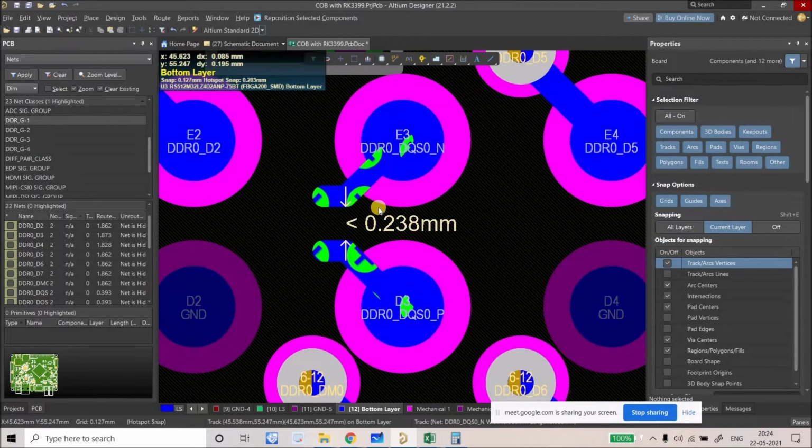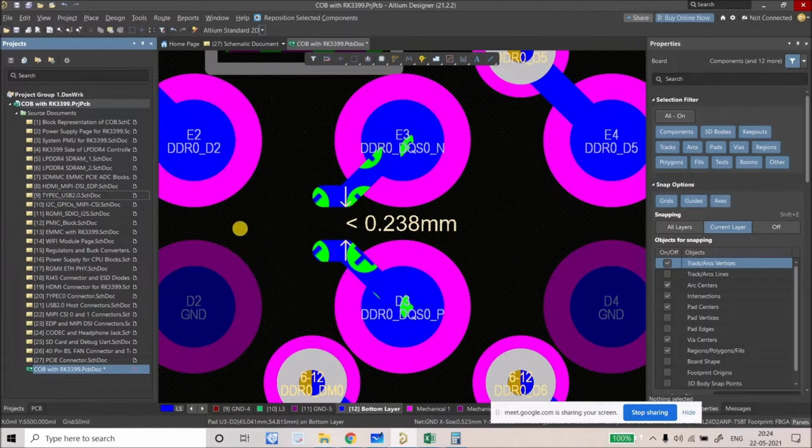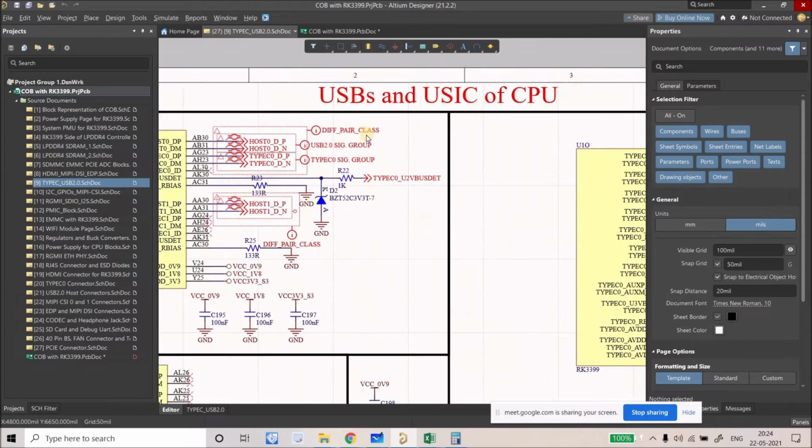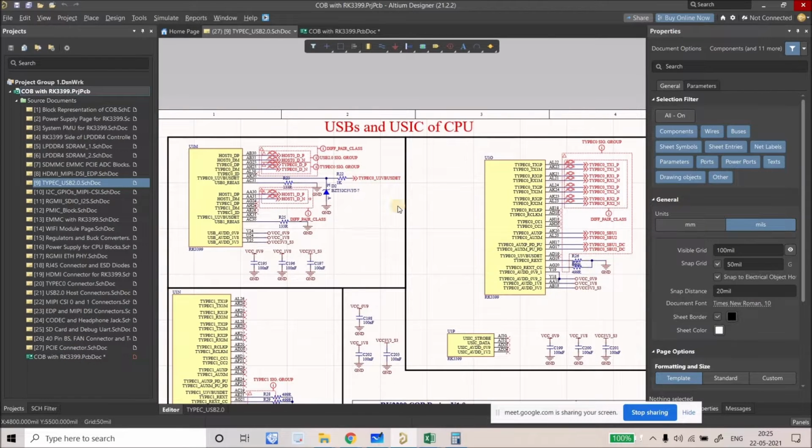If you remember from the clearance, we have implemented these rules. And if you remember this net class, I can show you this differential pair net class. I just forgot to implement this exception. This is one more exception for all the differential pairs. I'm just going to assign a very thin clearance between the tracks, and it will not follow the other rules, because there is no point in creating so many net classes. You can bypass that exception by creating different net classes for differential and single-ended, but there is no point.